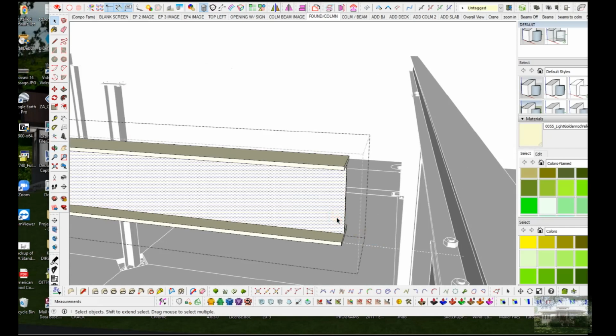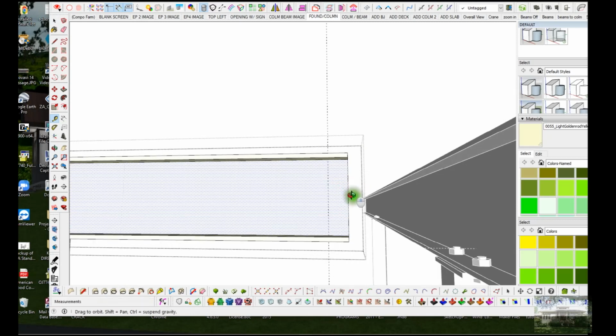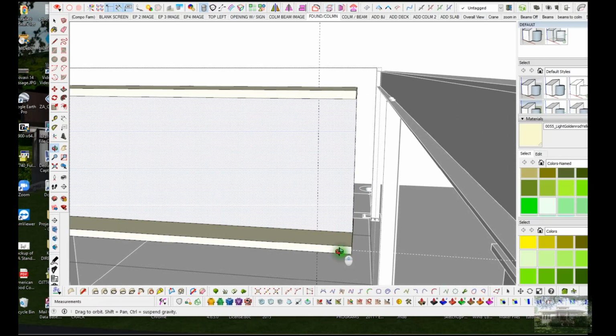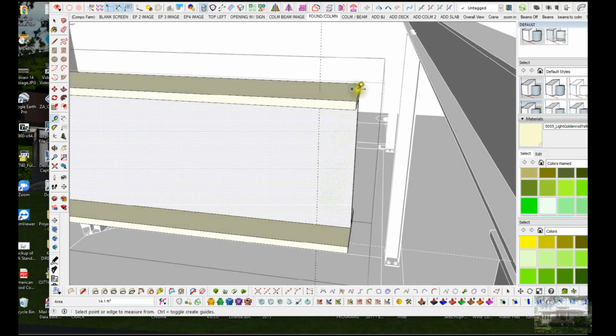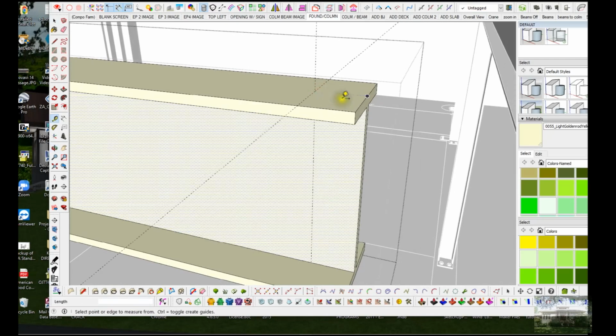So here again I need a cope. So I'll go ahead and put it on here. Eventually I can use this beam again. 2.75 is what it should be. 2.75, enter. There we go. So if you ever make a mistake typing things in and you don't do anything else first, you can type it over. That's all you gotta do is just type it again. You can even do it by, if you need to reverse the numbers, you can do that too.